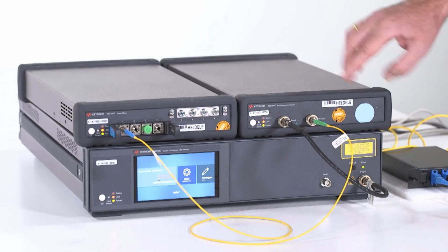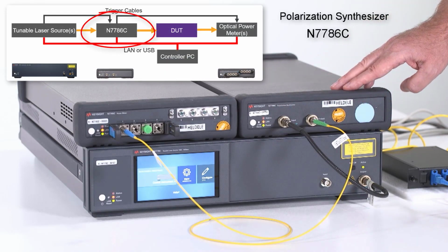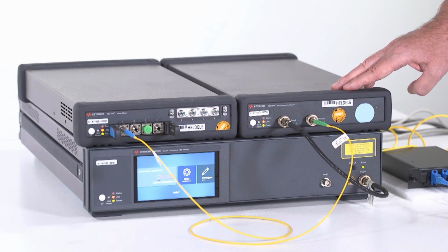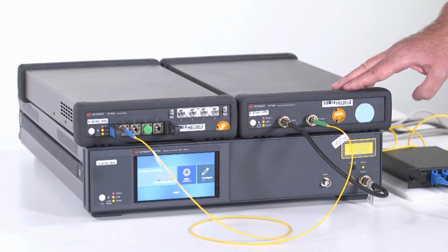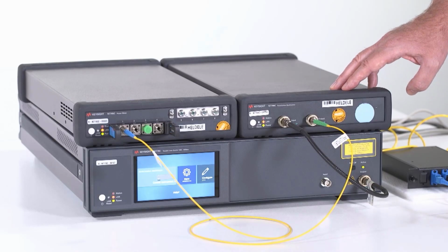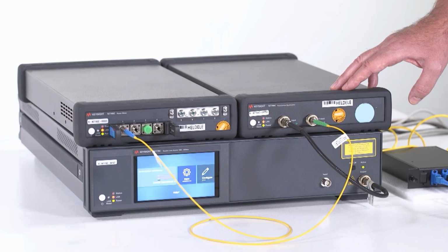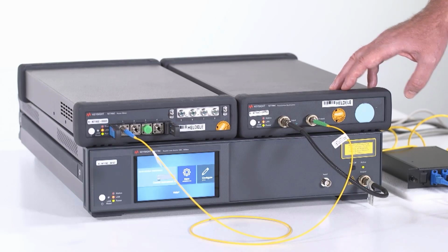And then we take the signal to a polarization controller. This is a special unit, or model, that can switch polarization very quickly and monitor and log the polarization at the same time, so that we can switch the polarization over a set of chosen polarization states while we sweep the wavelength, and therefore make a polarization dependent swept wavelength measurement with a single sweep.